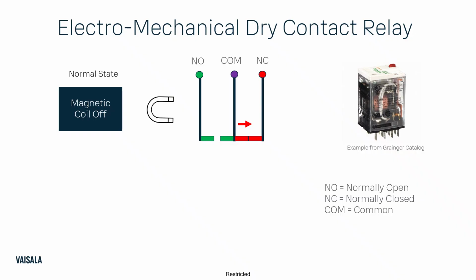So inside that relay, you're going to have three little wires that are in there, and each one of those wires that hang down are going to be connected to different terminals on the relay. You'll see them labeled on the outside as being NO, COM, and NC. NO means normally open. COM is the common terminal, and the NC is normally closed.